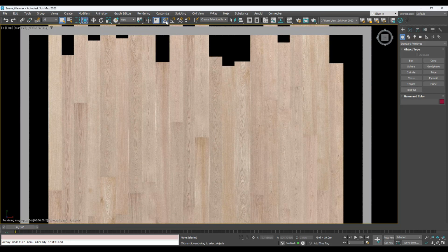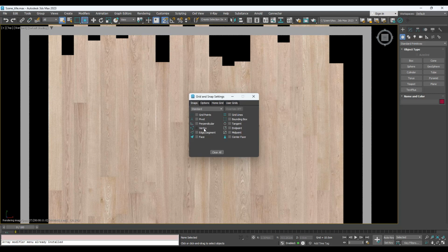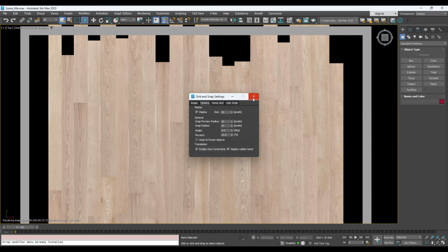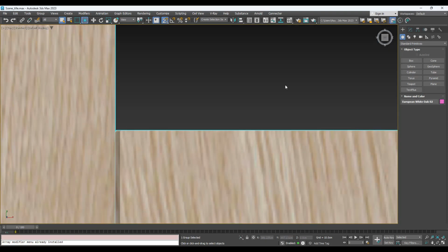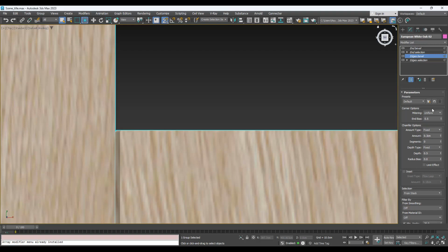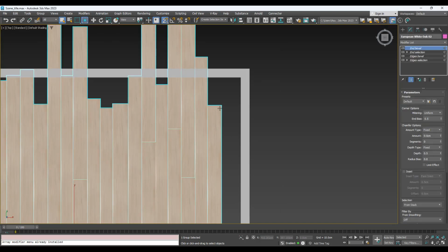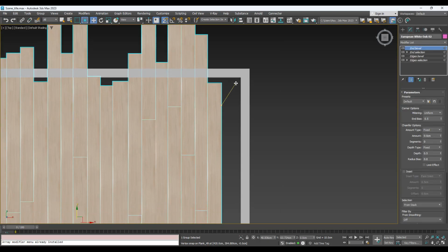Ensure the 2.5 snap is set and select Snap by Vertex and enable Axis Constraints options. These settings are not mandatory, so use those you feel more comfortable with. First, we will set the predefined edge beveling to 0 to make the geometry as simple as possible, making the snapping interactions easier. Then we choose a corner to start from and snap the whole group object.